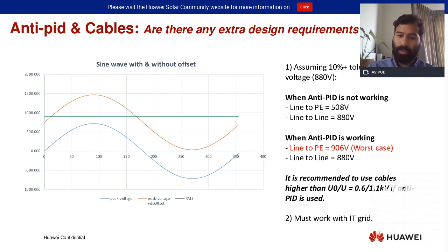If you get the confirmation, you can proceed with this cable, or simply get the next level of insulation, which should be around 1.8/3 kV. That will be the first point.